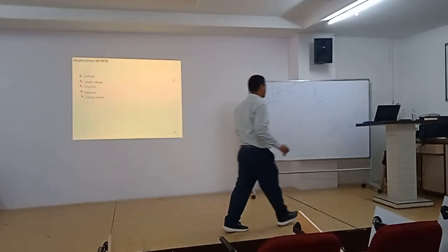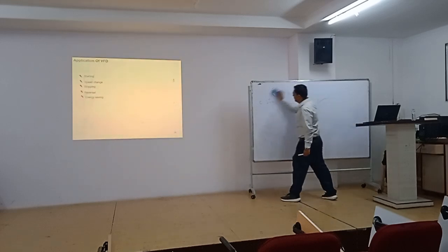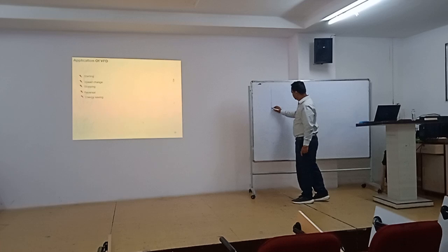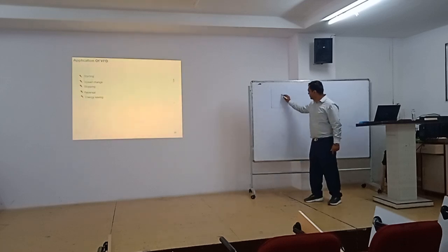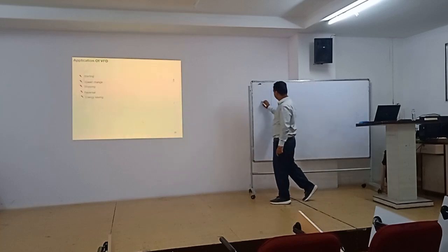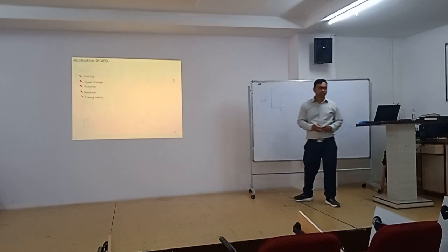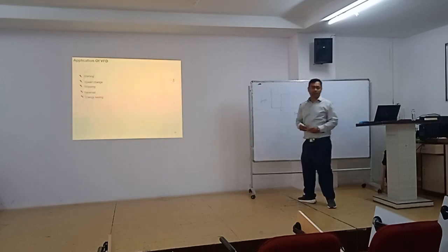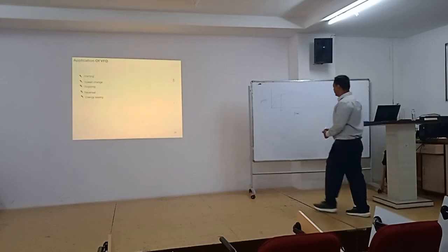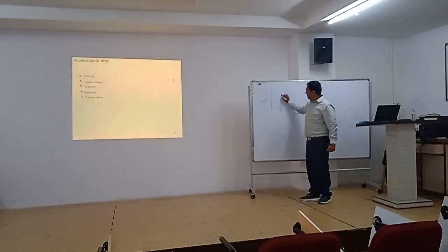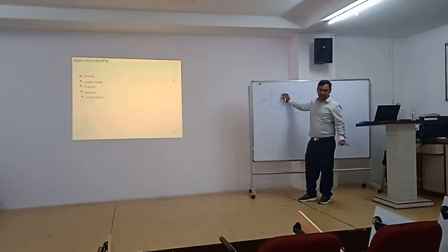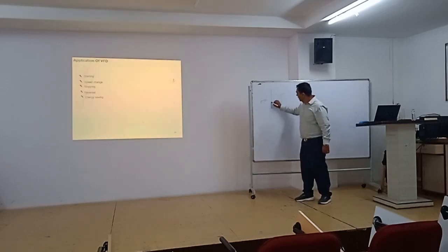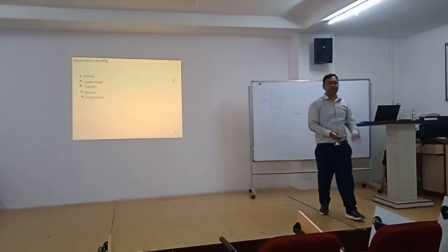And I think you might be knowing this curve. This is a very, very important curve. This is the power line. This is frequency. So why do we prefer VFD? One of the reasons is this. This is a power line. If you run at the rated speed, power will be the maximum power that the VFD will consume. But if you run at a lesser speed, the amount of power taken will be accordingly less.